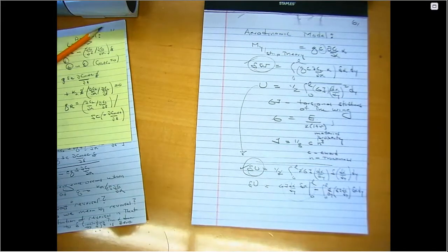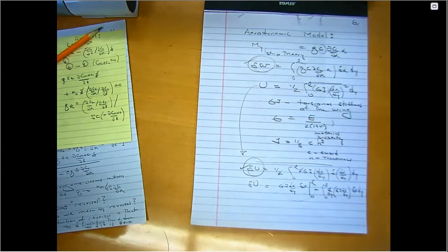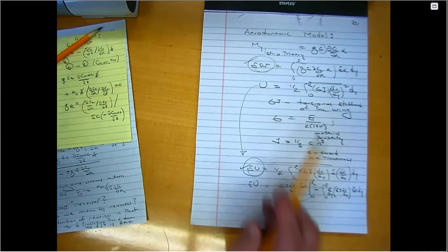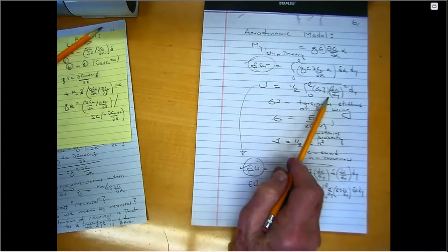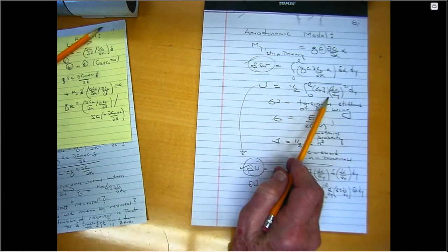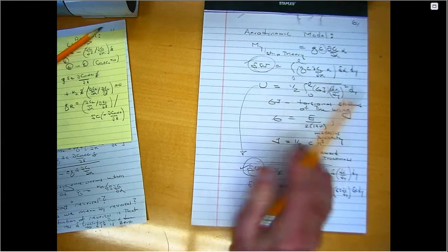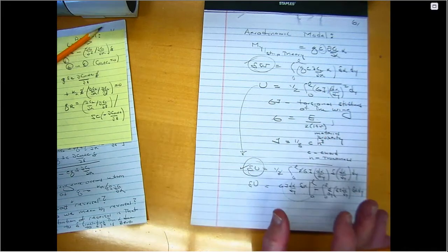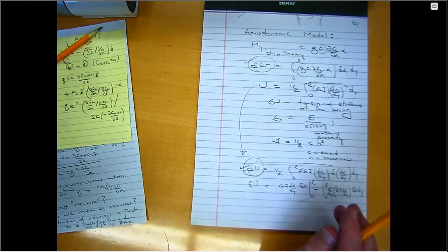Now, you might try to reason the boundary conditions by thinking physically, and that's fine. That's a good thing to do. But the nice thing about the principle of virtual work is it tells you what they are. In fact, it tells you the only thing they can be, because consistent with a certain representation of potential energy, the principle of virtual work tells you what the governing equation is. It also tells you what the correct boundary conditions are.